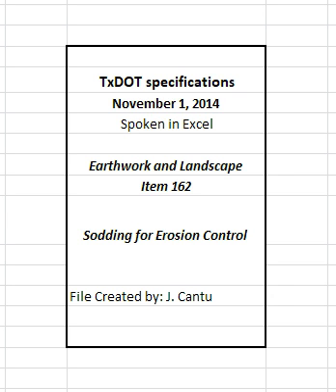2.6 Tacking methods. Use a tacking agent applied in accordance with the manufacturer's recommendations or a crimping method on all straw or hay mulch operations. Use tacking agents as approved or as specified on the plans. 3. Construction. Cultivate the area to a depth of 4 inches before placing the sod.